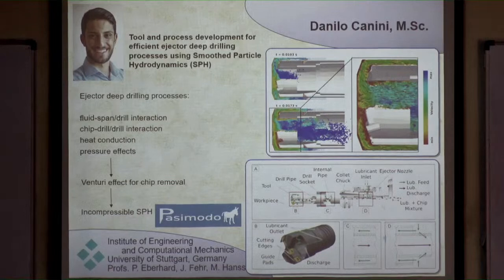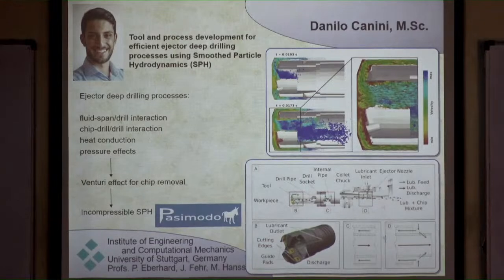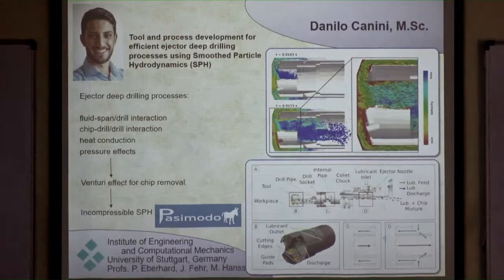This is another thing, a very complicated drilling tool. For example, if the interior surface of this borehole must be very, very smooth, then you can imagine if the chips are on the outside of the driller, they are rubbing on the surface and they are damaging the surface. So therefore, you need special tools where in the interior of the tools, all the chips are fed back. Again, a lot of simulation, a lot of modeling, a lot of experiments.